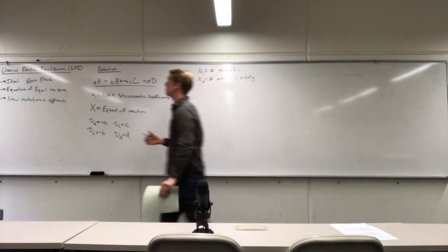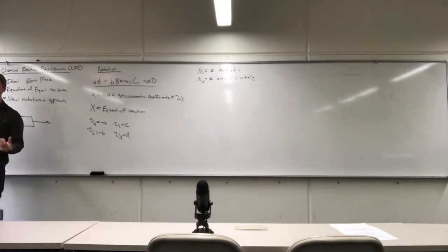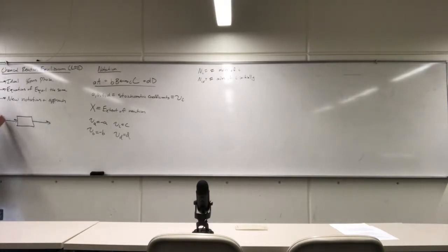So if we're modeling the system as a continuous system, now me being a chemical engineer by training, I always think of things as a continuous process. To me it's just easier to do the math. And oftentimes it's a lot easier to do the math if you're doing a steady state process. Because if you think of a mole balance, you have dN/dt, what's the rate of change of the number of moles? It takes away all the differential calculus. If you do things in a batch, in this case, this would be the initial or the in, this would be the final or the out.